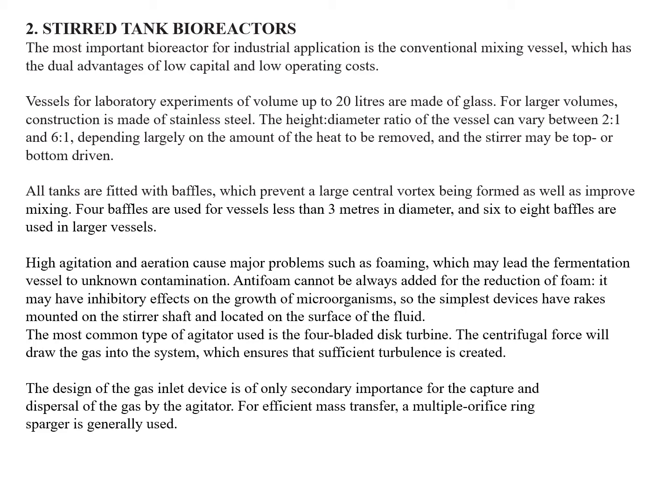And another one, to focus all the components into the center, is called baffles. Baffles also facilitate the mixing process with the help of the impeller. Once an impeller is there, the baffles have to be used automatically, or otherwise the rotation will make all the liquid components form a cyclic movement of liquid, and the mixing process will not happen much.